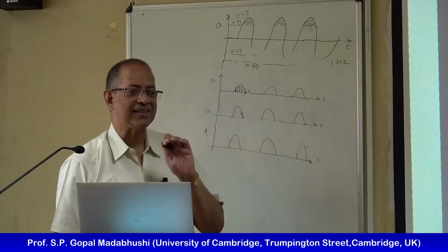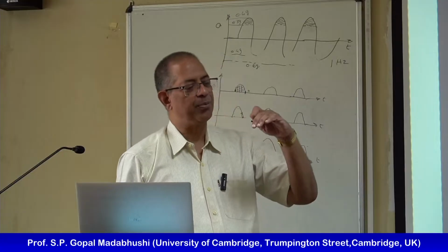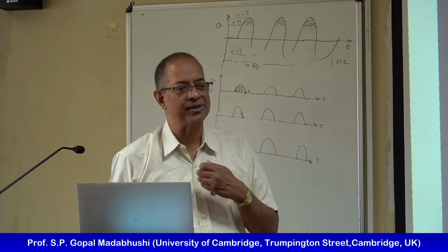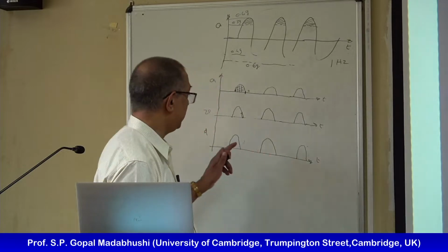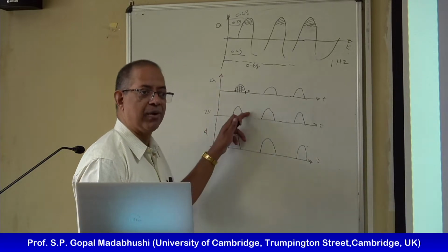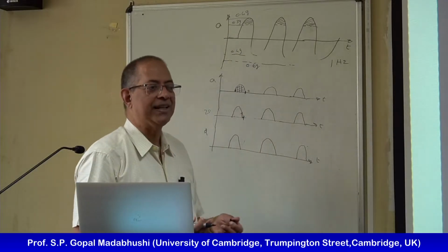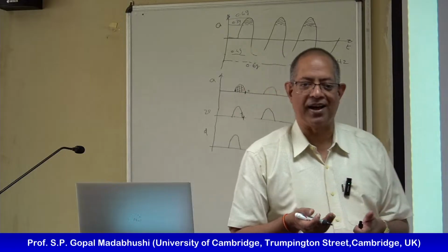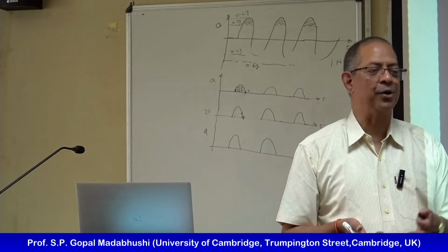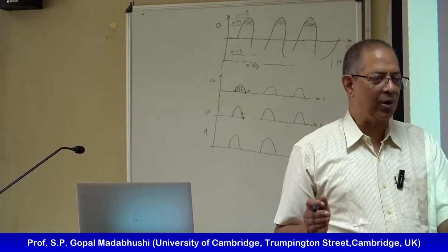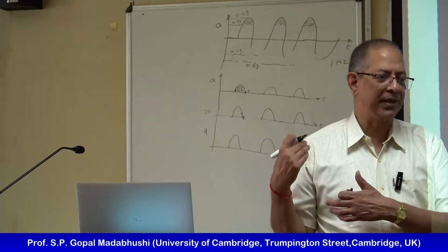The fact that acceleration has come to 0 means the body is not being subjected to acceleration, but it still has some velocity, right? So the displacement will accrue until velocity comes to 0. It's like stopping distance for a car. The stopping distance you calculate not based on acceleration or the braking force, but based on velocity coming to zero. It's the same thing here.